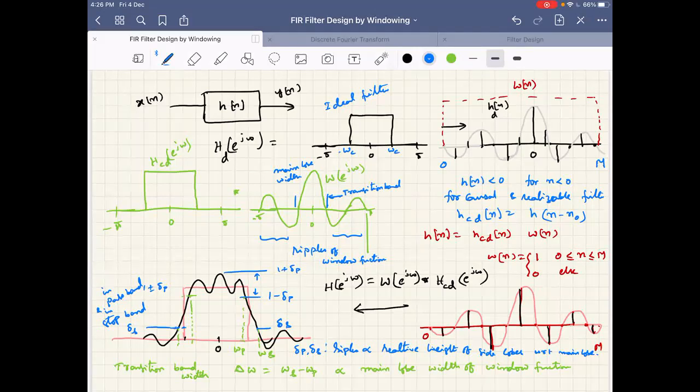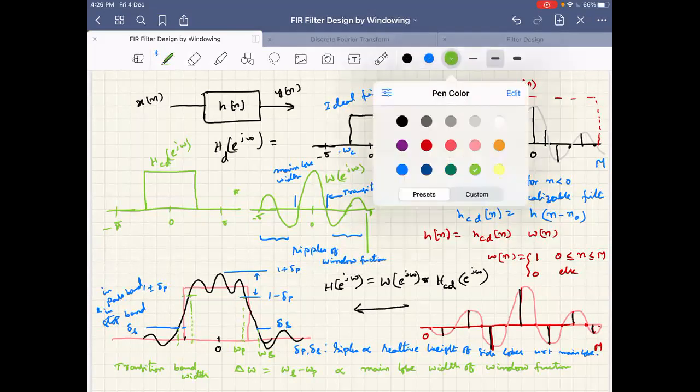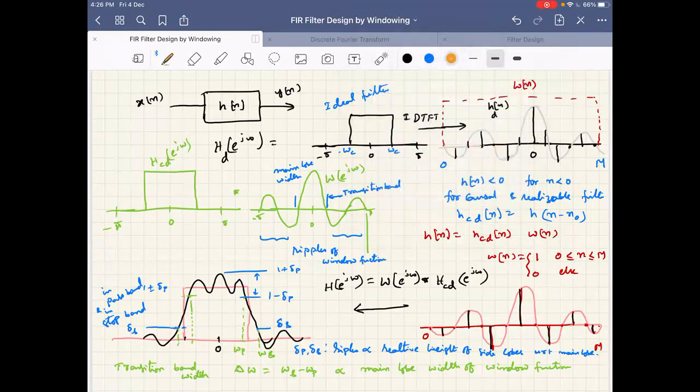So what we are doing here is the discrete time Fourier transform. In fact, this is the inverse discrete time Fourier transform. And you have got this, and this process is referred to as windowing. Again, all this process that we are writing here is windowing. Bringing causality, and then this is windowing.